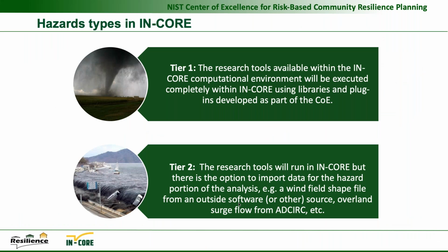So there's really two types of models that are essentially possible. One is a model that's self-contained in the analysis, and then the other is essentially importing a raster or importing the hazard. And this could be something like ADCIRC, which is the Advanced Circulation model for overland flow, and this is what's used. It's likely being used right now to predict Hurricane Laura's inundation and things like that. And those are run as fast as they can on supercomputers right before events, as well as for planning.